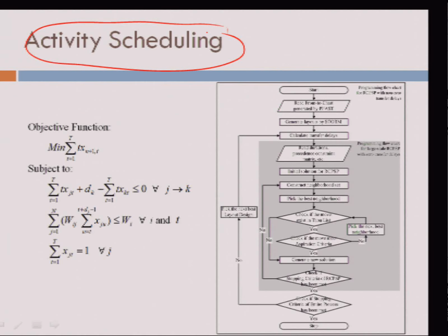Please go back to what we've been saying about Job Shop Lean: it is implemented the same way as you would implement the Lean thinking process of Womack and Jones. Identify value, identify a value stream, change the layout and material flow inside the value stream, then schedule execution inside the value stream. Similarly here, if you look at a process activity and you're trying to improve, say, setup, you look at it as a process, you change the workspace in which the setup is done, and then you try to improve the scheduling of the various activities.